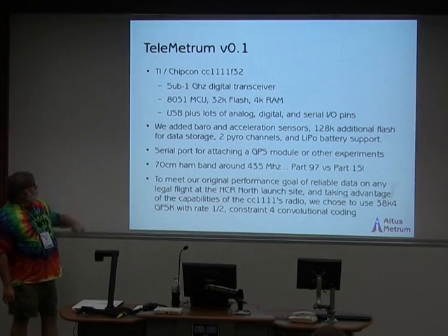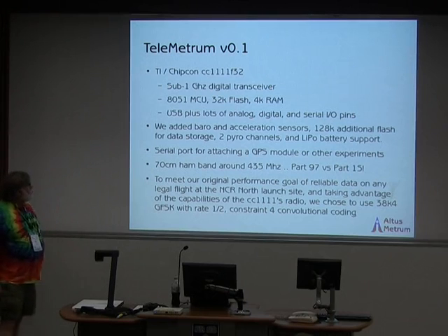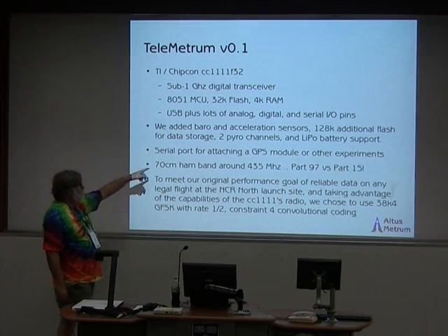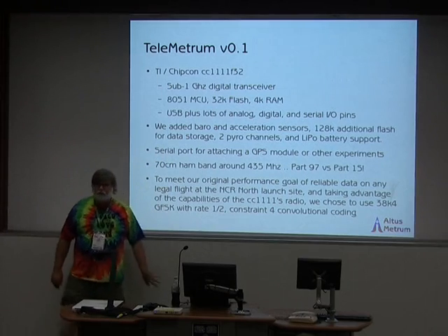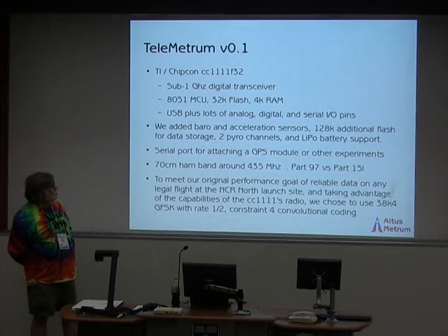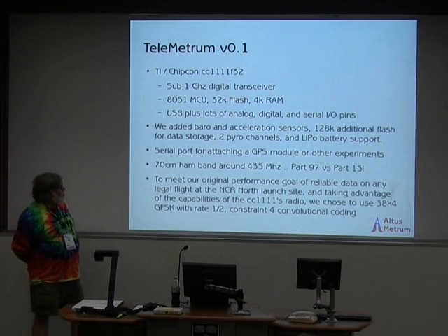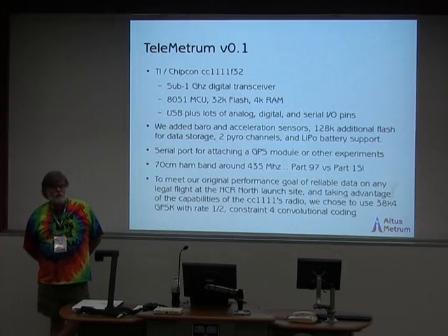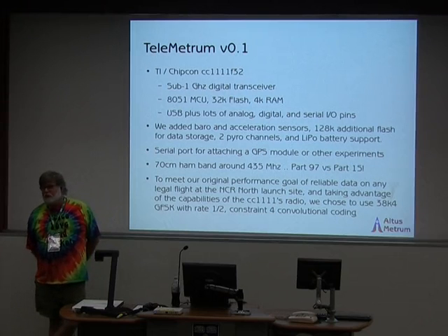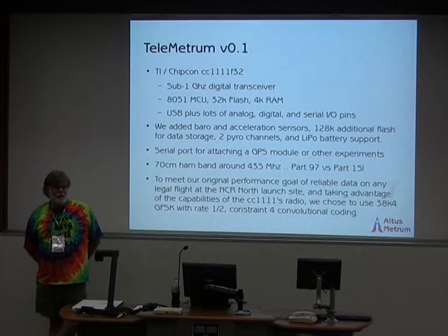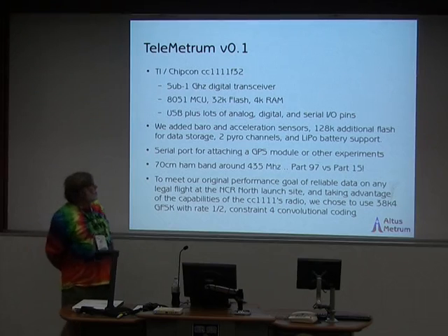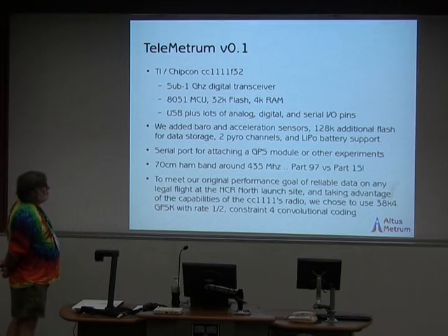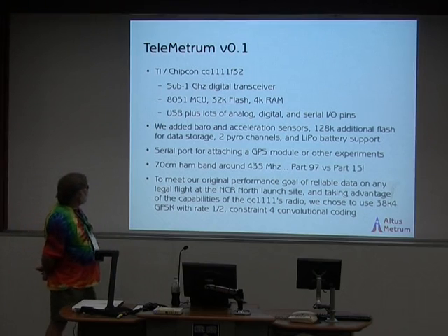So we added some baro and acceleration sensors, some additional flash for data storage, a couple of FET circuits for firing pyro charges, and some LiPo battery support. By the way, the LiPo battery support I hadn't even thought about until I gave the talk on my original board design at LCA. I don't remember who it was in the audience, but somebody in the Q&A session stuck their hand up and said, have you thought about using lithium polymer batteries? And so I sort of owe my intrigue with LiPos to that session.